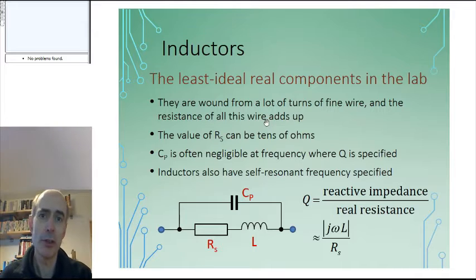If you can design a circuit which needs to be frequency dependent, but which uses capacitors rather than inductors, then you will find your design task much easier. The equivalent model of an inductor looks like this. This is a typical model used. The inductor itself is there. There is what can be quite a large series resistor there, and an overall parallel capacitance here.